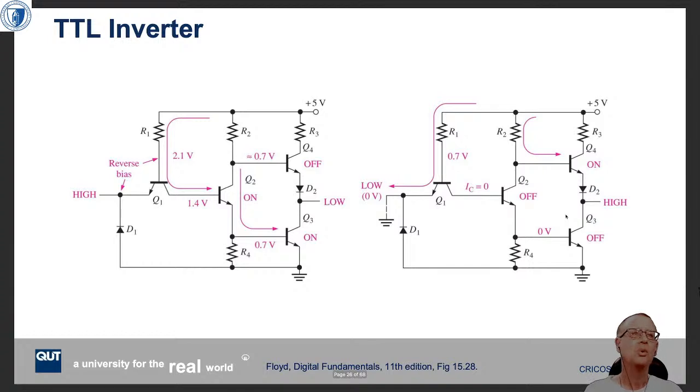And this is just some more about how TTLs work. So look at the difference between, this is just a simple TTL inverter, right? And you can see it's got transistors, BJTs rather than FETs, and it's got resistors in it.